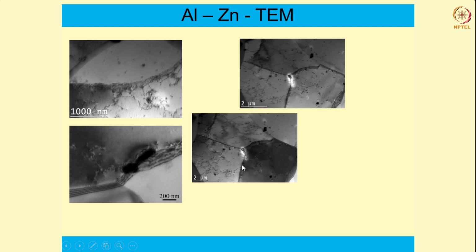So this boundary is already turning into a high angle grain boundary and creating a small grain inside this bigger grain. Okay, same thing would happen to these two parts also whenever these boundaries turn into high angle boundaries. And how this transformation from low angle to high angle boundaries occurs, that also we have discussed before.